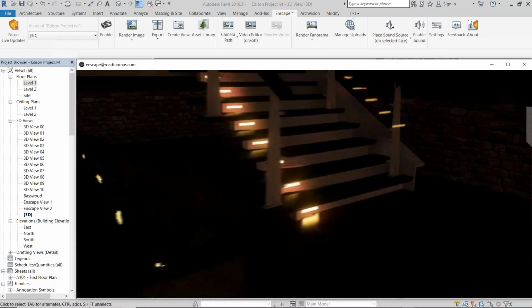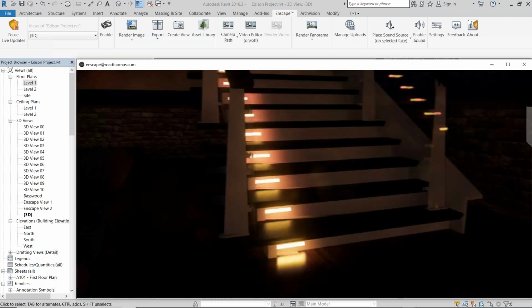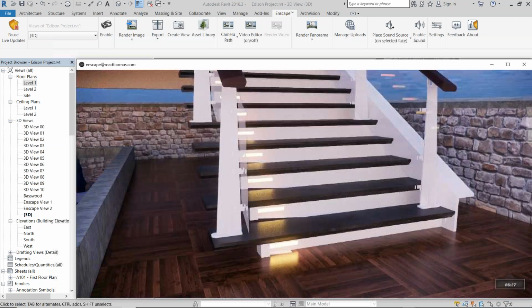There's a really practical application with illumination in Revit in that you can't nest a Revit light family inside of a system family. So your stairs, your balusters, your railings, I'm noticing a lot of those conditions actually have very fine, subtle illumination now via LED lighting or some strip lighting. And it's not possible in Revit to nest those system families with lights and have them behave predictably. So in this case, we're just building a bit of geometry, applying a material to it.